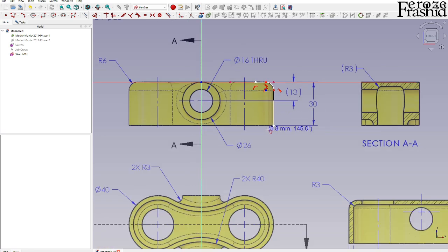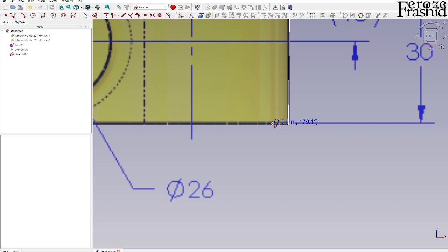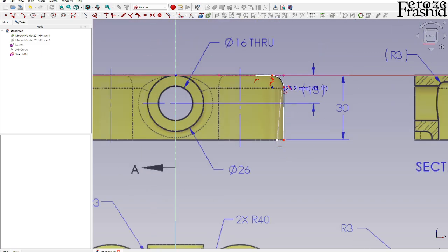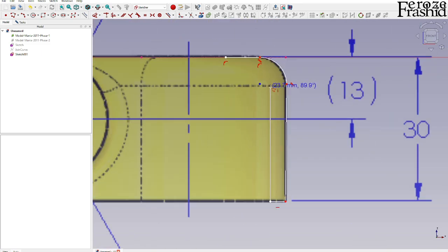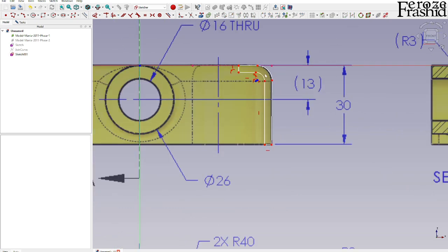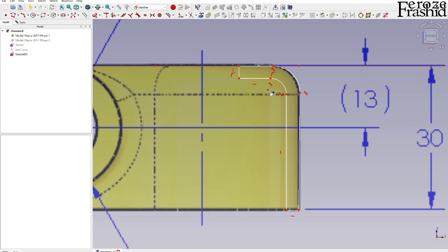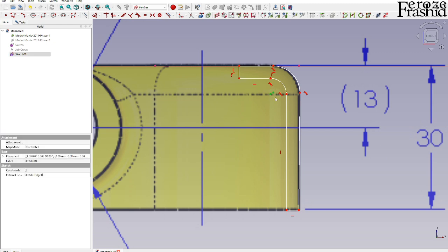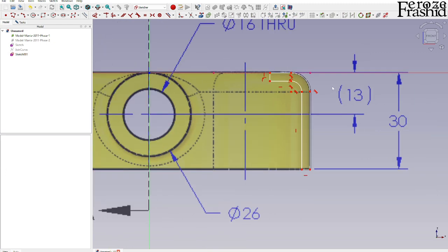And so this thickness of the wall is 3 millimeter, so we want to come around here 3 millimeter and bring it back vertically, make another arc, right, and sort of close it right here. Okay, so this is going to be horizontal.